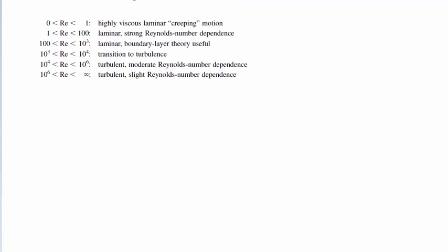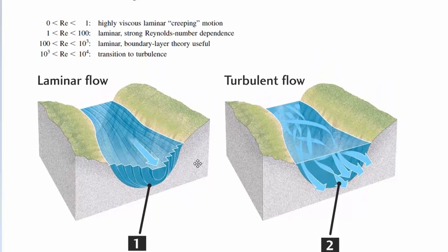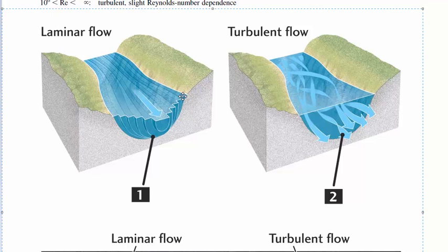So again, you saw that graphic before. This one, I think, I just Googled it, looks even better at explaining what everything looks like. So notice how in this laminar region, everything tends parabolically toward the center. So you have the maximum velocity of the flow straight through the center of your pipe. And then on the edges, they're moving slower because there's viscous drag from the roughness of the pipe acting on there.